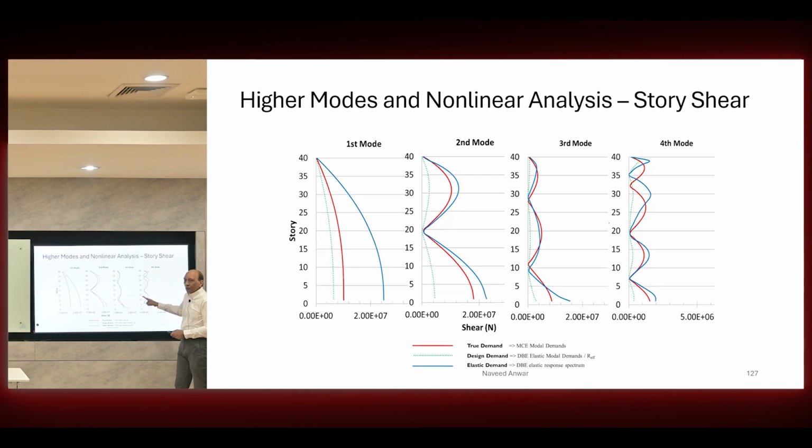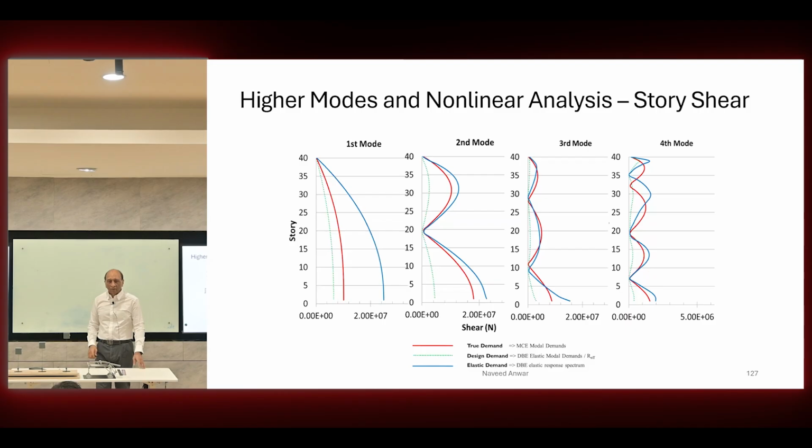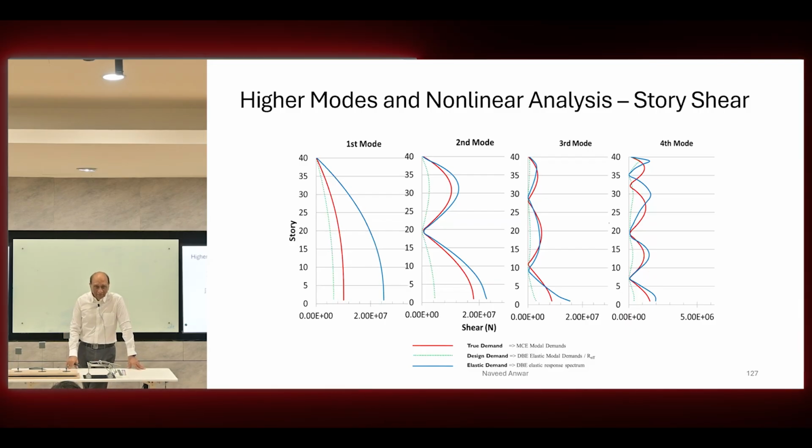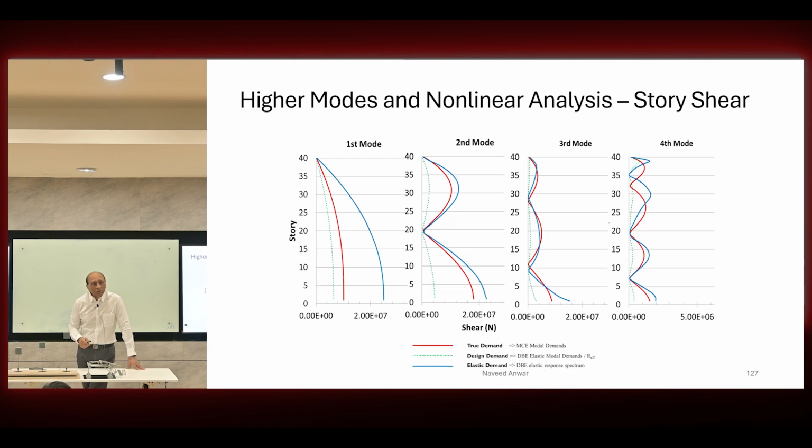So there are going to be portions of buildings where, first of all, there'll be no yielding and there should be no R, or R should be just 1 or very small. Three or four PhD students did a lot of work to find this out. They produced a lot of results, and that's how the code in Thailand is going to be changed. Many people are realizing that you cannot reduce all the modes by the same factor.